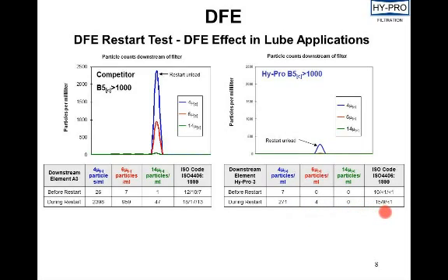We want to be providing servo cleanliness fluid, ISO fluid cleanliness codes at all times, even during restart, even during dynamic stress points over the life of the filter, which we're achieving here of 15.9, less than 1, even after the filter is fully loaded and we hit it with a restart test, which is the worst condition.